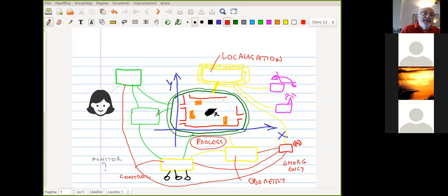So all these, and of course the planner, the trajectory of the motion planner, that asks the robot to generate a trajectory moving in the environment, basing on the map of the obstacles and the position of the goal and so on, the position of the robot. And also this is the general graphic interface by which an operator decides which commands and which is the goal of the action.